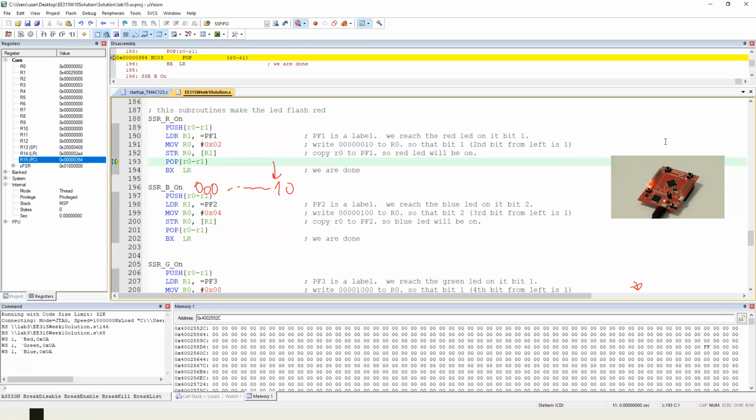Well, yeah, it may confuse you, but LDR is to load to the scratch registers. Store is to store the value of the registers to the memory or where memory points. So think of registers as inside the microprocessor, and memory and devices as outside. So registers are inside. LDR is loading to inside. STR is storing to outside. Okay, so get used to it. The only way to get used to it is to just do these codes hands-on. I know that you're doing it, guys, but as you do it, you get used to it.